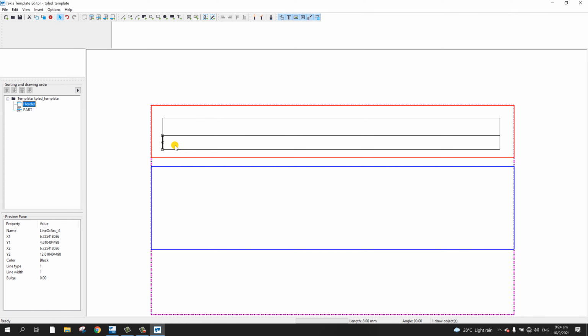So what I will do here is I'm going to press Control D, and then you will see there the duplicate object. There is an offset of horizontal and vertical. Horizontal is going left or right. Negative going to left, positive going to right. Vertical going up and down. So I need to copy that one to the right side. So I'm going to put here 15, enter. All right, Control D again, and then type here 15.